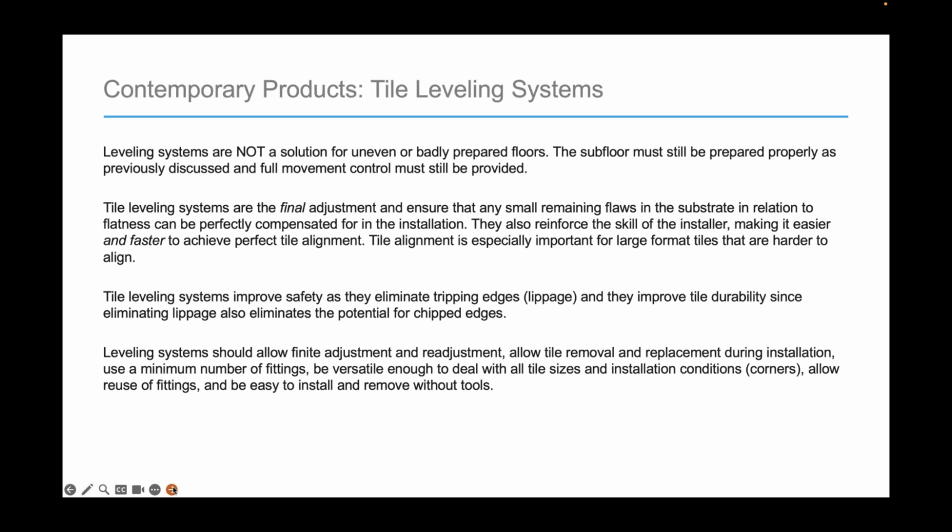Another contemporary product is the tile leveling system. We have a lot now. Leveling systems are not a solution for uneven or badly prepared floors. The subfloor must still be prepared properly as previously discussed, and full movement control must be provided.